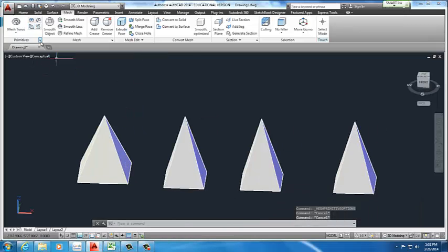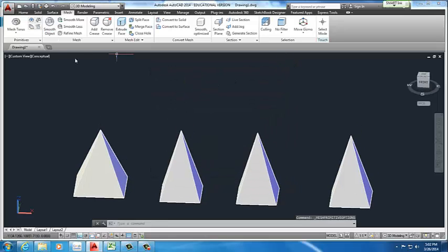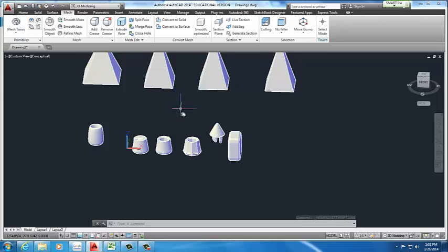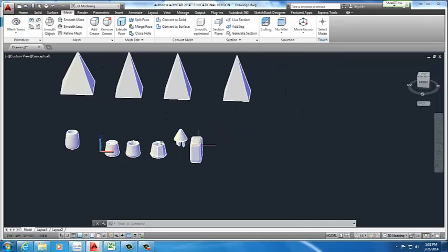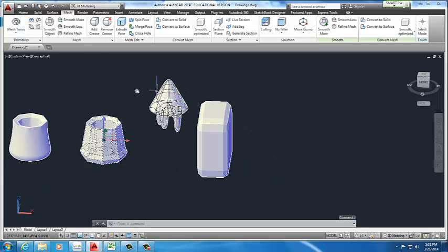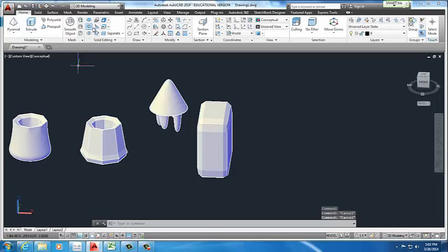So if we go into here, we can set up how many lines we get per each object that we use. So torus, how many axes, how many heights, so forth. And so that's an option. Another thing a student pointed out is that these are not solid objects. These are surfaces. So if I slice them, let's go to the slice command.